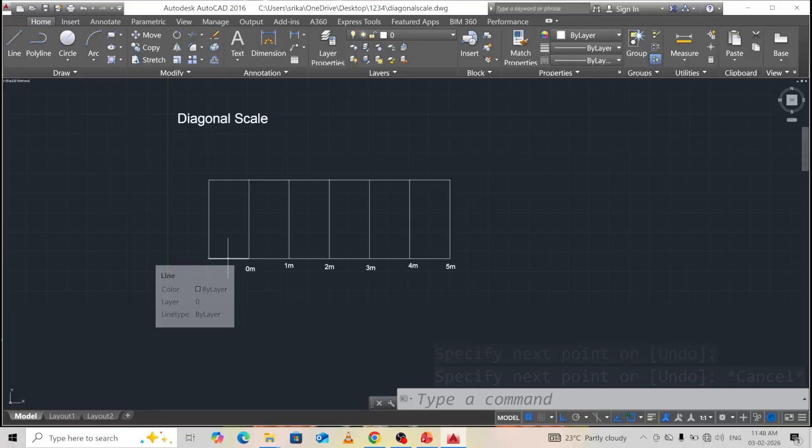Then you can select that particular box. Because of this, only this line is highlighted, and only this box will be divided into 10 equal parts; otherwise the entire line would be selected. For example, if this line were not drawn, the entire length of the line would be selected, and the divide option would become a very typical process.